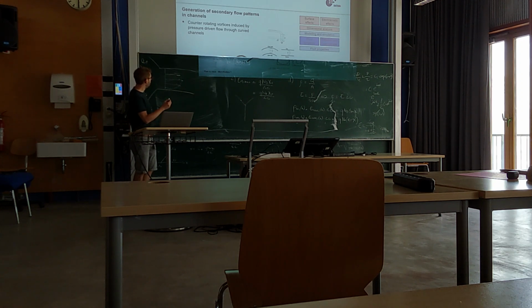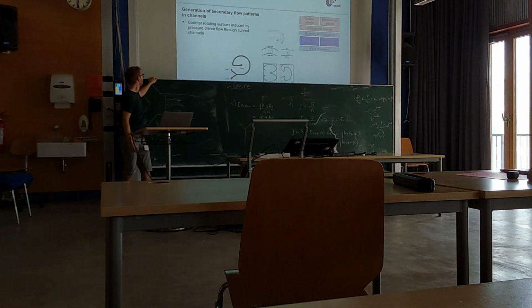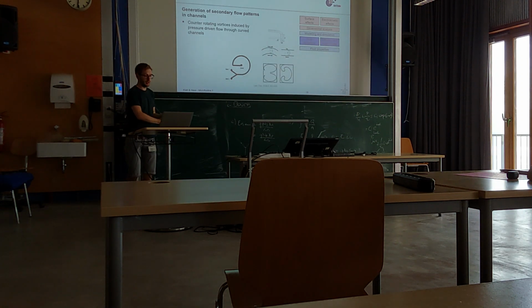So the basic idea behind the mixing approaches I'm going to show you is that we want to generate some kind of secondary flow pattern, meaning that we superimpose another flow field onto this fluid, so it starts to mix, we form vortices and so on. And this is what I mean with the generation of secondary flow patterns.